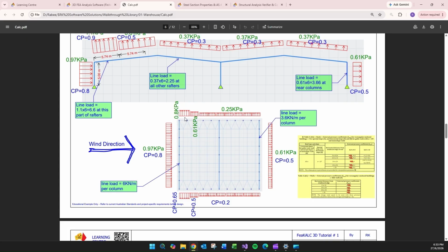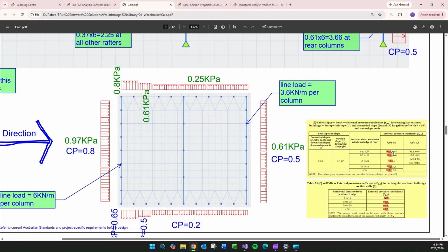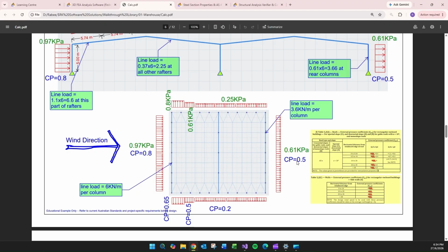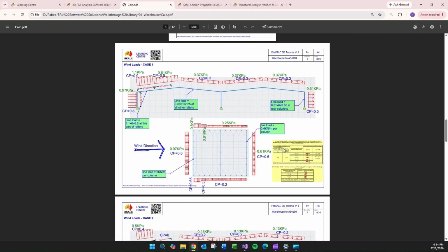Always on the corners, there will be a magnifier, roughly 1.5 of the wind applied. You need to apply certain scenarios, so it will be like minus 0.9 Cp and minus 0.4 on those zones that you'll see on the standard. So scenario one would be this. Cp is the factor multiplied by 0.6 times V squared, which is the wind loading.